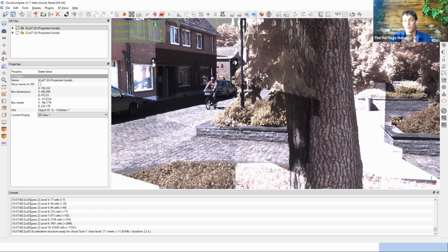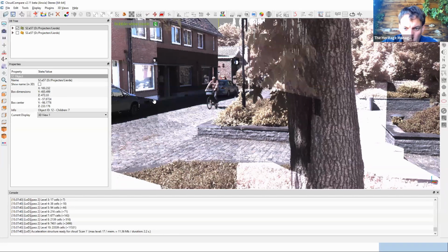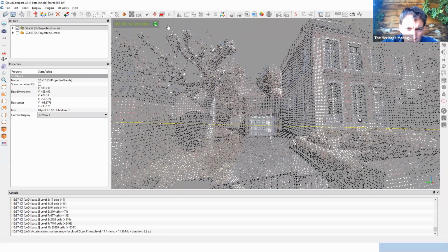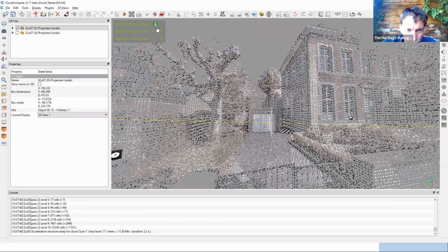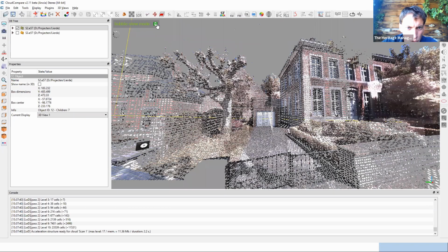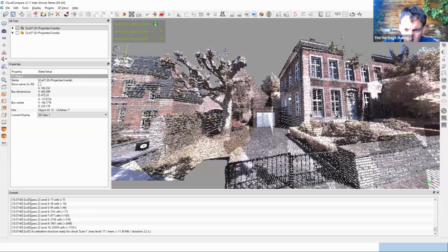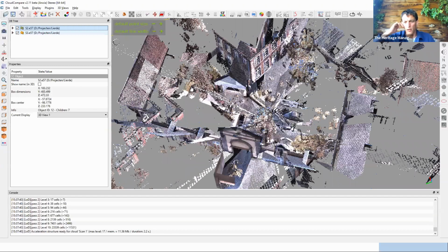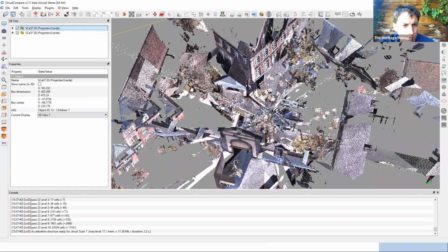So with photogrammetry, we discussed black and white targets. In laser scanning, you can also use black and white targets, but there are some other different targets as well that can be recognized automatically by the scanner. And I use these targets to do the automatic registration of my point clouds. And that will allow you to generate a spatially coherent view of your object. If I get out of this point cloud and I take the point clouds again, then at the end you will see that all point clouds are nicely aligned.